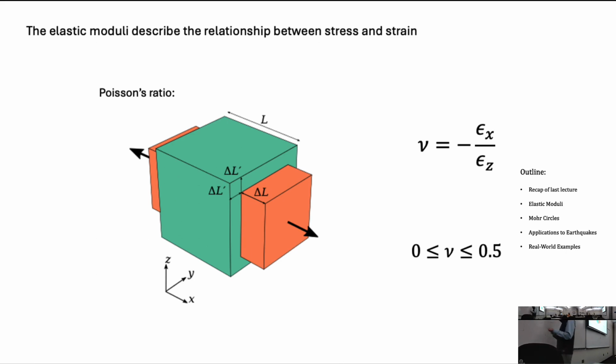And so what that means is if you take an element and you apply a stress to it, and there's axial strain, as we saw with the Young's modulus, what happens to the other dimension? Any guesses? So you have an element, you apply a stress to it, it strains, which is the epsilon x, and then the epsilon y in the other dimension. What do you expect the strain to do in the other dimension? You probably have some familiarity with this. Yeah, usually it gets bigger.